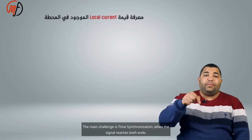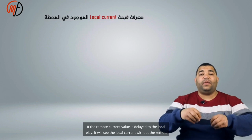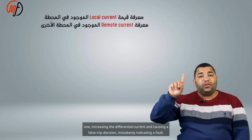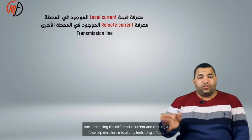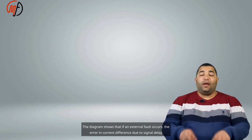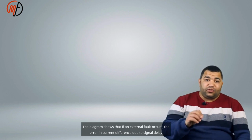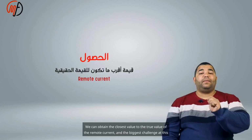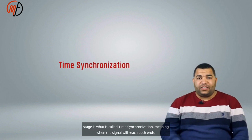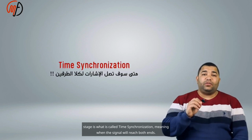When the signal reaches both ends, if the remote current value is delayed to the local relay, it will see the local current without the remote one, increasing the differential current and causing a false trip decision, mistakenly indicating a fault. The diagram shows that if an external fault occurs, the error in current difference due to signal delay increases with delay time.